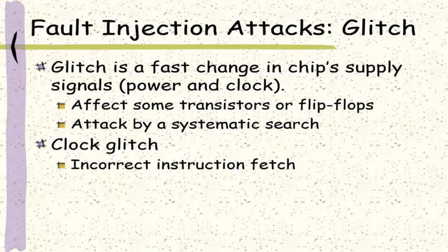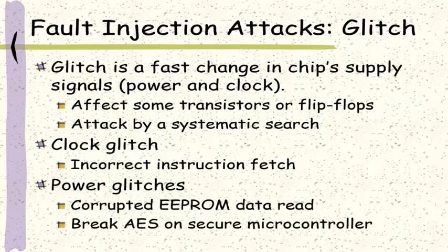And power supply glitches can break a 128-bit AES key in 2^12 attempts, which is about 8 hours at a 100 millisecond cycle. If we do it selectively at carefully chosen time slots, not continuously, the number of attempts can be reduced further to 2^7, or only about a couple of minutes.